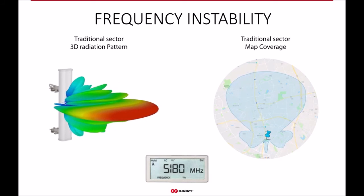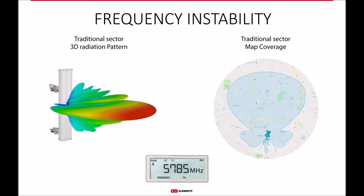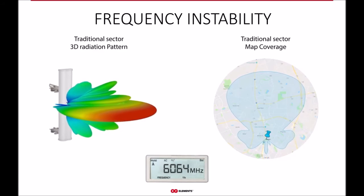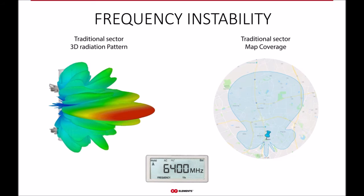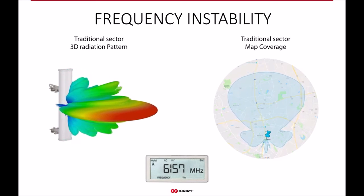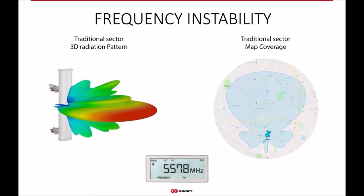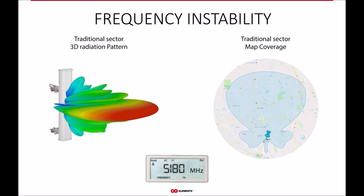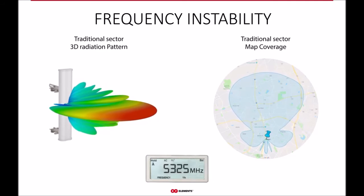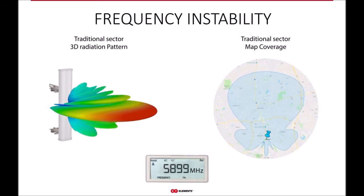And the main beam width changes with frequency, which is yet another addition to the instability of the coverage provided by patch array sectors. So see on the animation how the side lobes are pulsating and regrouping. It is exactly this feature that makes the patch arrays so unreliable and random. Switching between the channels often changes the link performance quite significantly. So patch arrays are unstable in the whole unlicensed spectrum WISPs use.